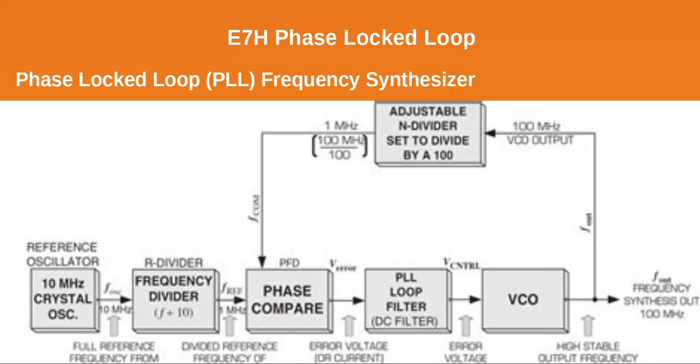That's analog. Before, they were almost all phase lock loop because the circuits weren't fast enough. Your clock has to be a lot faster than the output signal, 3 times desirable.